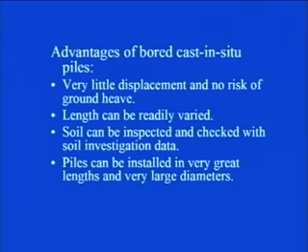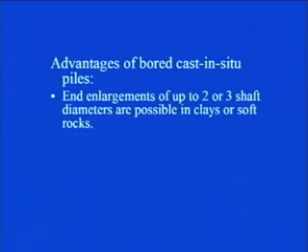Piles can be installed in very great lengths and very large diameter. This is one of the main advantages of bored cast in situ piles. End enlargements of up to 2 to 3 shaft diameters are possible in clay or soft rocks.